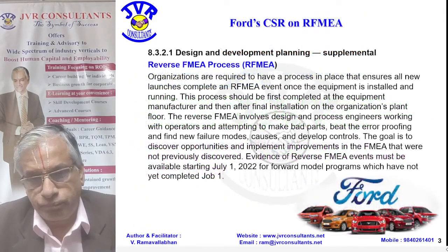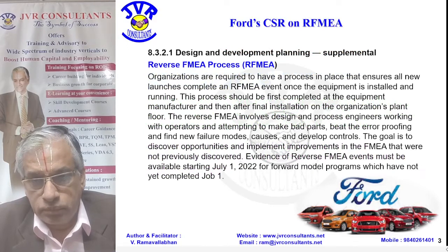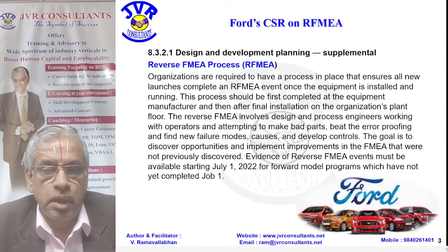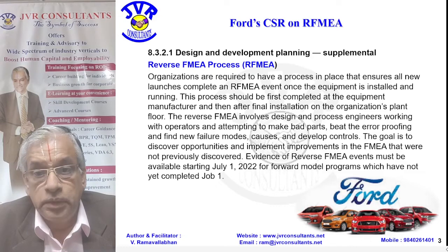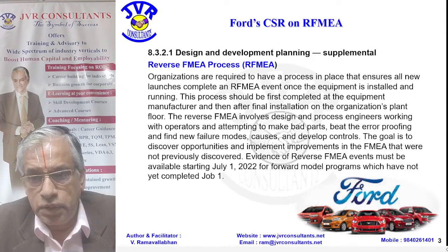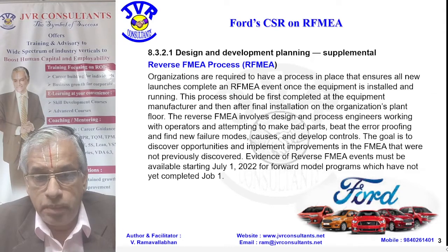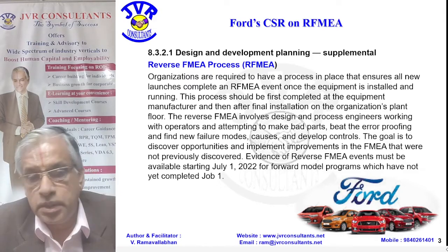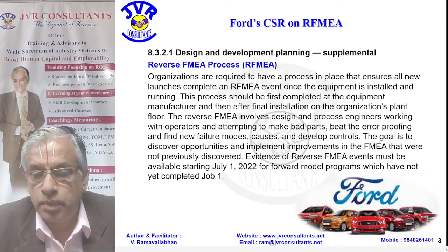So in this line, the Ford CSR, customer specific requirements, says: Design and development planning supplemental, reverse FMEA process. Organizations are required to have a process in place that ensures all new launches complete an RFMEA event once the equipment is installed and running. The process should first be completed at the equipment manufacturer and then after final installation on the organization's plant floor.